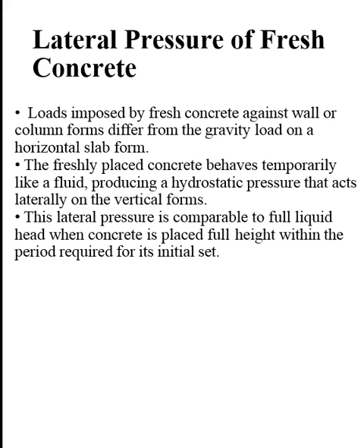Lateral pressure of the fresh concrete goes to how long the concrete placing operation is going to be. The loads imposed by fresh concrete against a wall or a column are different from the gravity load on a horizontal slab form, that is after the concrete is hydrated, it's solid. The fresh concrete behaves at least temporarily like a fluid, so you get hydrostatic pressure laterally on the vertical forms, and it's as if you've got liquid head. So again, once the concrete hydrates, the force goes straight down, as a gravity load on whatever footing you have.